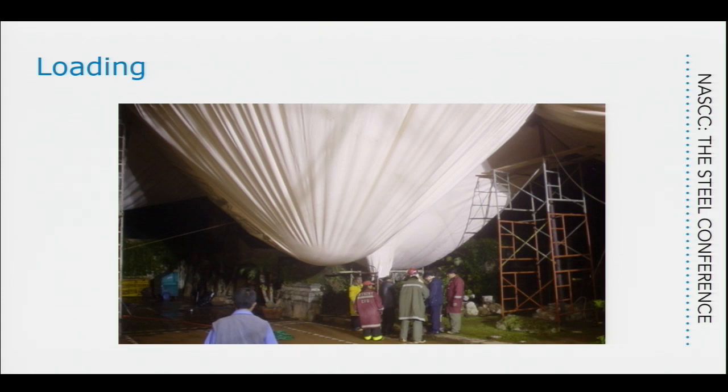And it's kind of like you would design any roof in Denver, right? You design it for a certain amount of snow load, with the assumption that there's a peak snow load, and after that it falls away depending on your slopes. Now here it gets a little more tricky, right? Because snow loads are dependent on slope, and if you saw our structures, the slope varies quite a bit. So we have to do a lot more work. Yes.